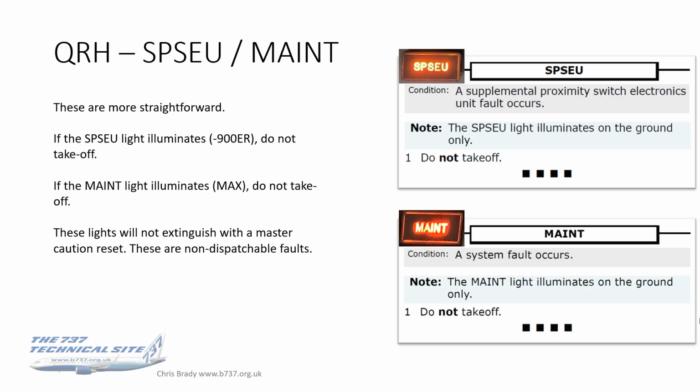With the SPSEU light and the maintenance light, it's all far more straightforward. If it illuminates, don't take off. End of story. These lights will not extinguish with a master caution reset, and they're non-dispatchable faults.